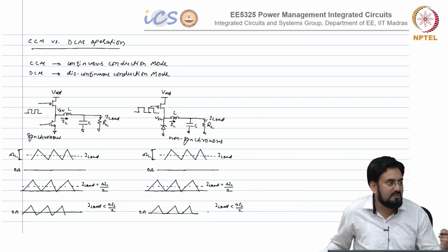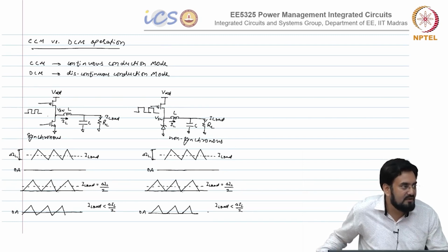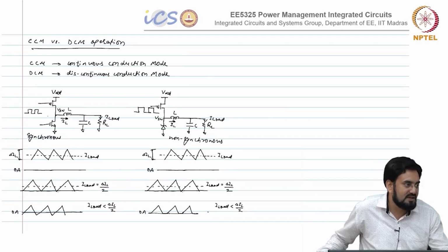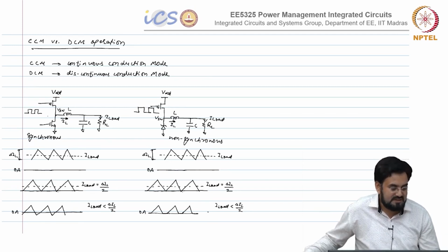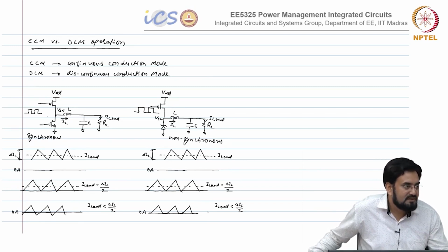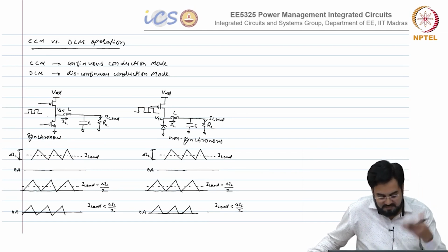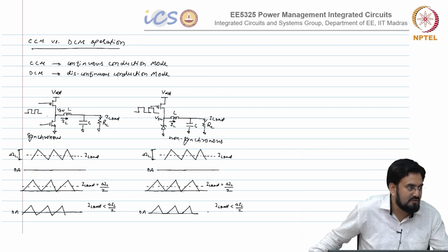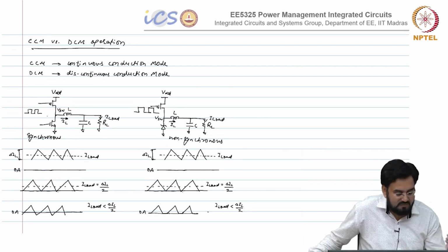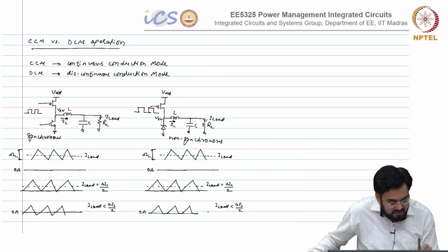The moment you turn off the bottom switch, it will behave like a diode, because it will not allow the reverse current, and which means you are able to implement an ideal diode with this switch with some extra logic.